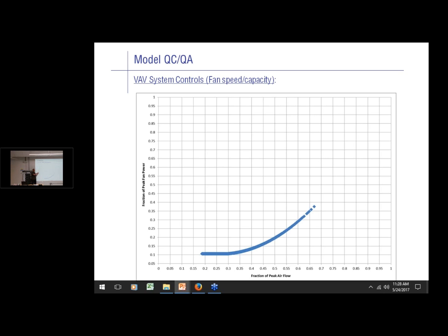I would question this model. I would immediately think I'm not estimating appropriate amounts of fan power in this model. It's underestimating. If you're underestimating fan power, then all your fan efficiency measures that you're playing with, like going from VAV to a radiant heating system, you're underestimating the fan savings associated with that as well.